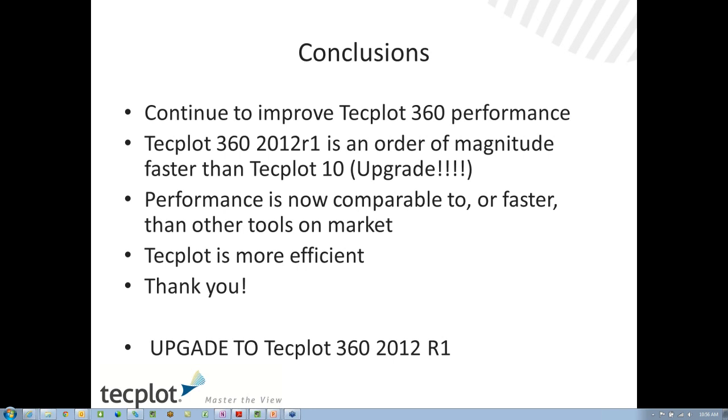And yes, for overflow, if you are computing all your non-conservative variables from your conservative variables, which is a plot3D format thing typically, and overflow is essentially a plot3D format, then you do need to load more data. But there are techniques that we're working on that allow you to load less data than the full amount. It's true certain file formats require you to load more data than other file formats, but I don't think there's any format that requires you to load all the data.